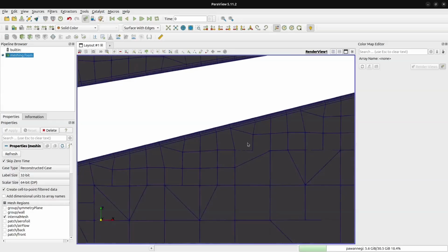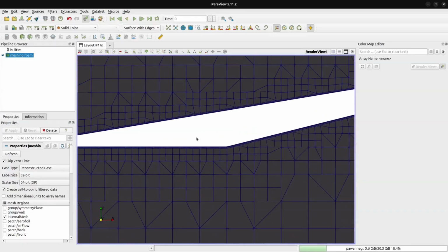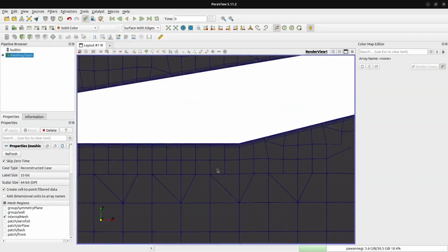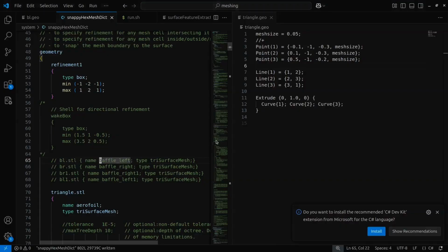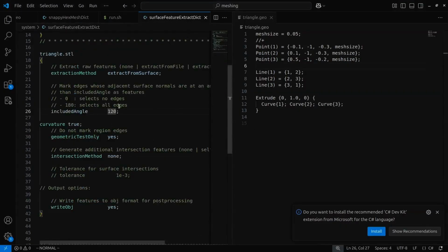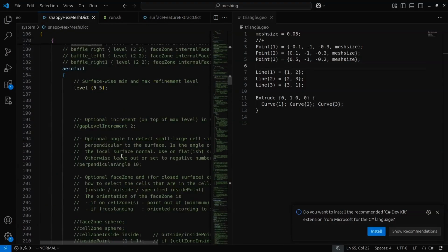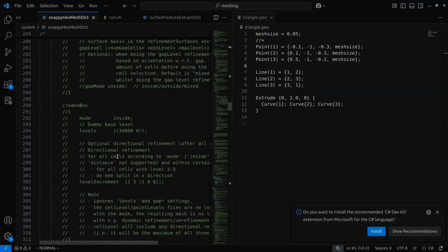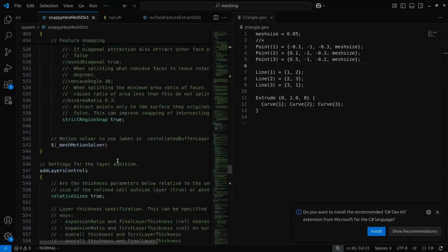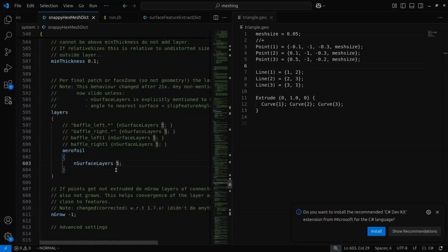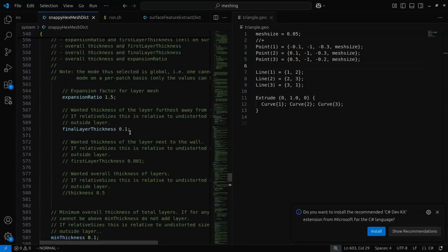In order to show you that sometimes it does not create a good mesh here as well, I'll just change this, which is the surface feature angle, to something else. We are going to try the following change such that we do not have a good mesh on the surface. We change the number of layers to say 20, and this will change to 0.3.